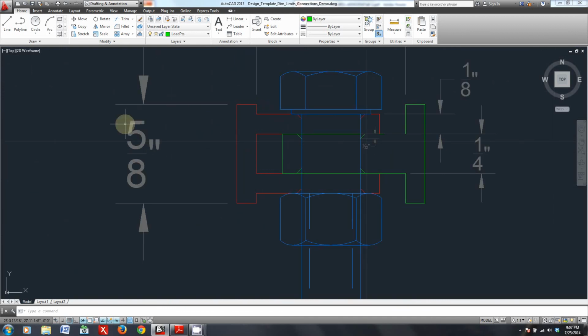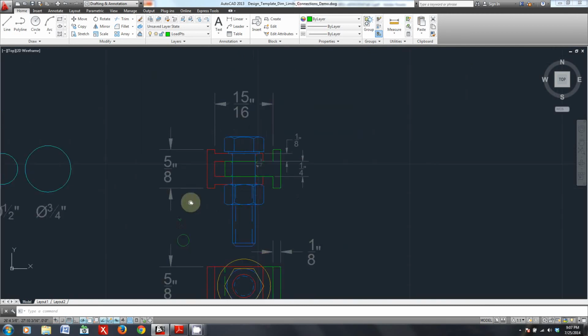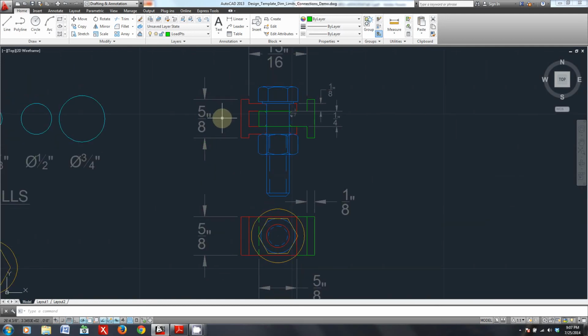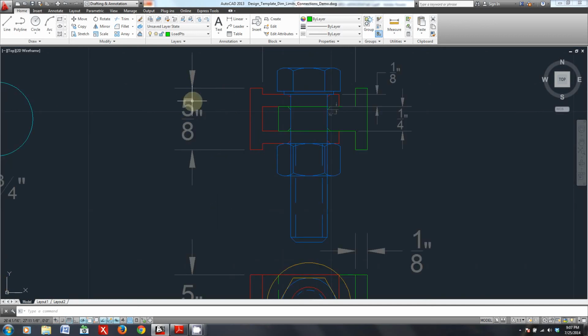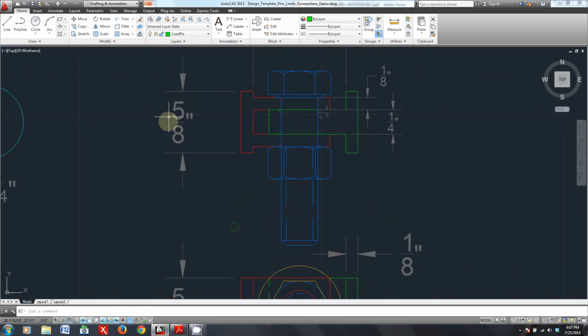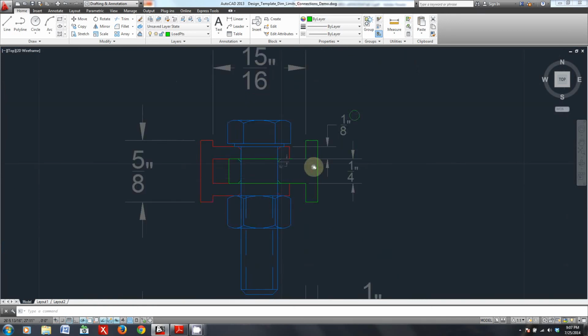If you had a 5/8 by 5/8 square bar, and I definitely would recommend a cold rolled bar because it's work hardened, so it's a little bit tougher, that would be basically perfect for these kinds of connections. You usually want to keep them within some dimension that feels characteristic. So 5/8 sounds like a good round number.